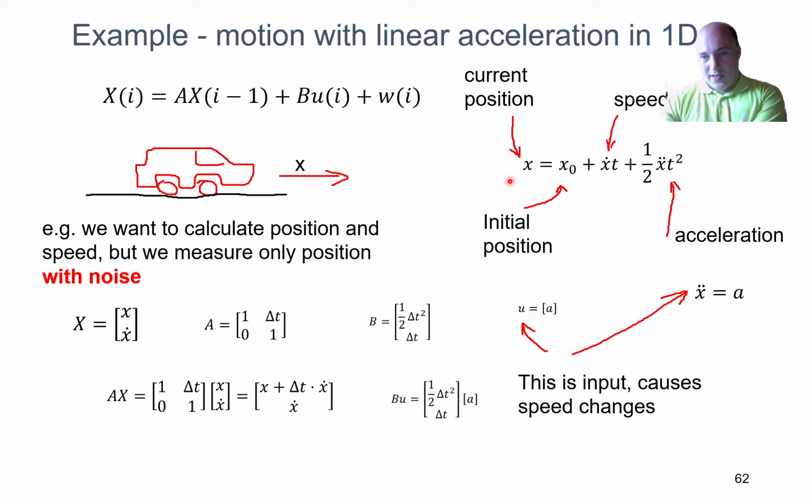Now what's the point in using the Kalman filter if I am able to create such an exact model of my system? Well, the point is that the measurement always comes in with some noise. So my sensor data is always noisy. So although I will have some exact mathematical description of my system, I need to filter out the input signal so that I have an estimate with a smaller error.